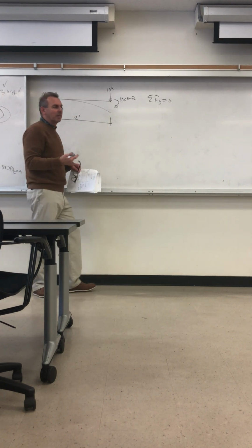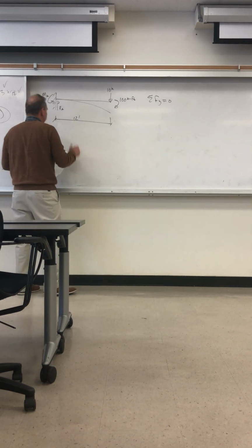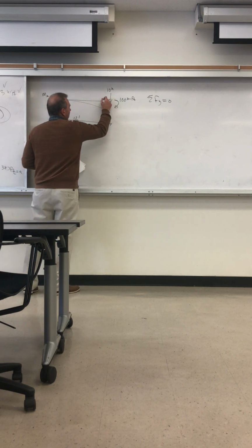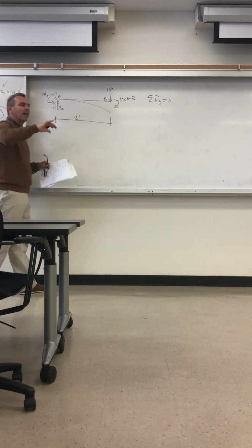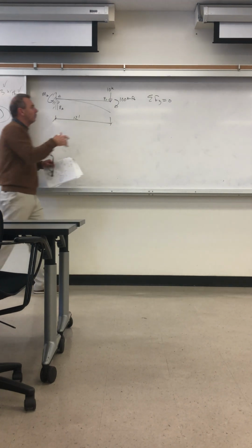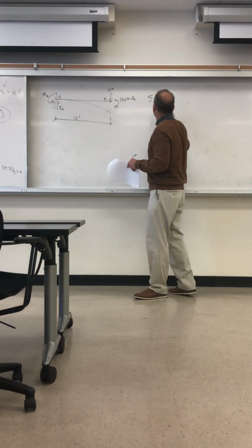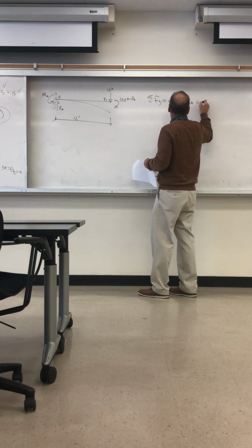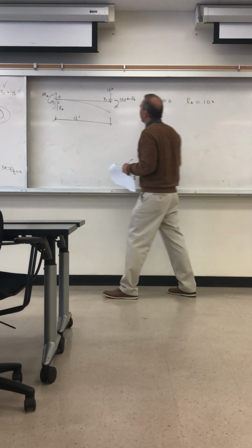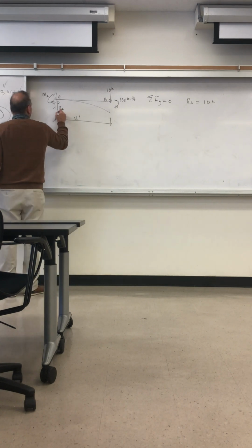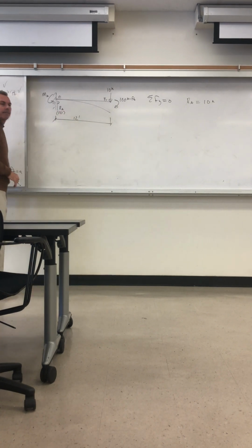We're applying two things on the right side of B: a vertical force of 10 kips and a concentrated moment. But this is a moment, not a force. So when we sum the forces to get reaction A, it's just equal to 10 kips. We're not adding in that moment of 100.